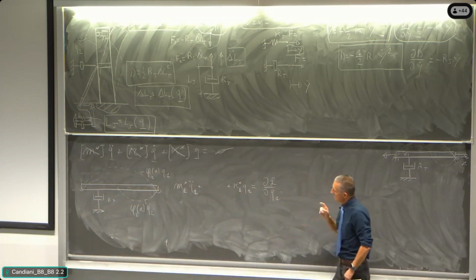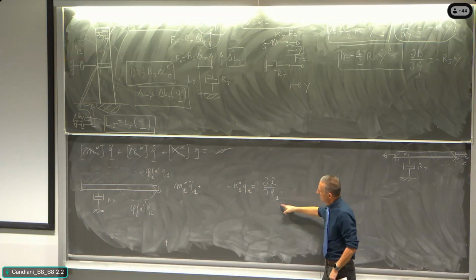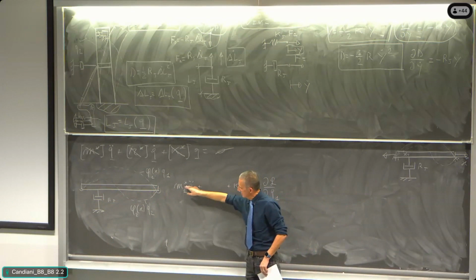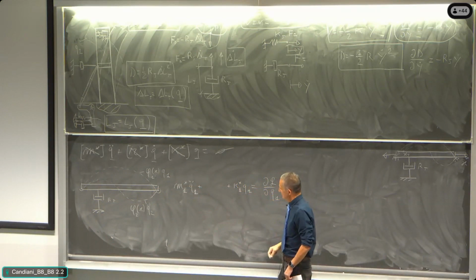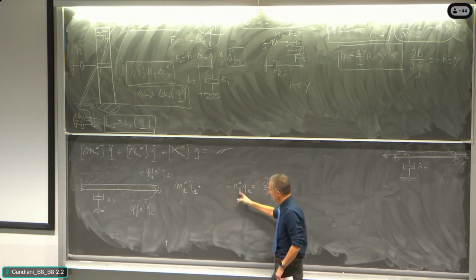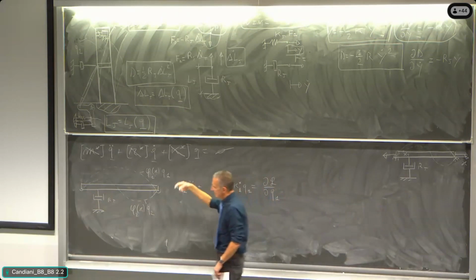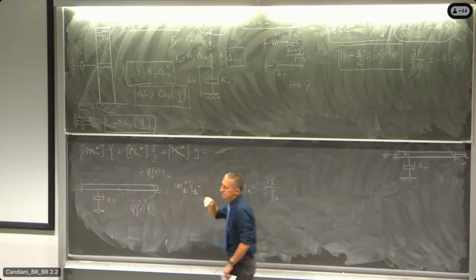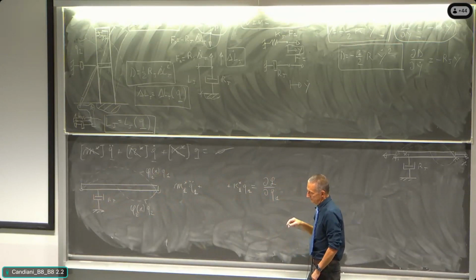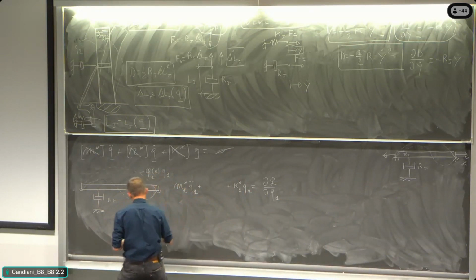So let's think about writing the equation of the first mode of vibration. We know that we write the modal mass of the first mode, the modal stiffness of the first mode. This is the principal coordinate, second order derivative, zero order derivative. And then we have to write the work of the external forces due to the virtual displacement associated to the first mode. And so, which is the external force that is acting?